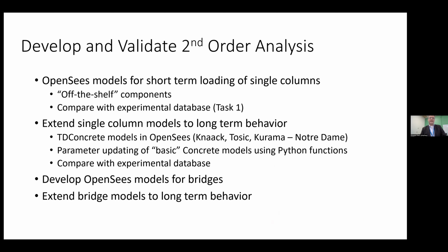Okay, so we'll use a lot of off-the-shelf OpenSees components for short-term loading with single columns, and then compare with an experimental database, which I'll talk about at the end, and then also extend to long-term loading behavior using some recently developed models in OpenSees for time-dependent concrete behavior, which incorporates shrinkage and creep.